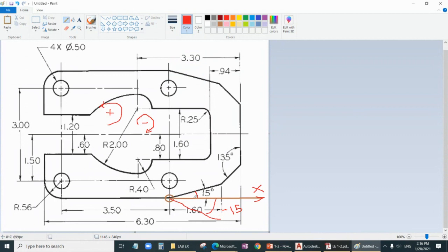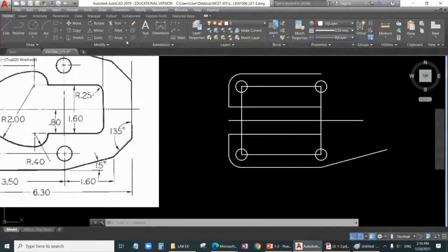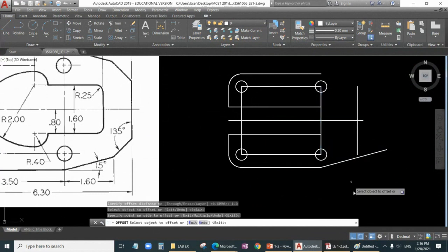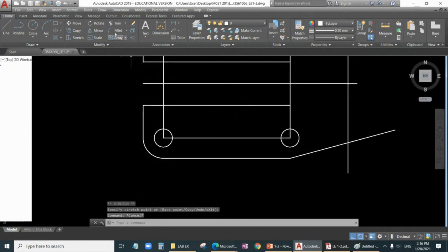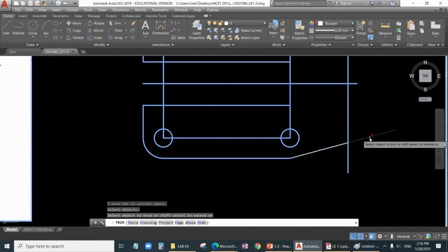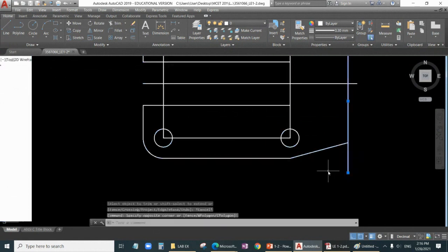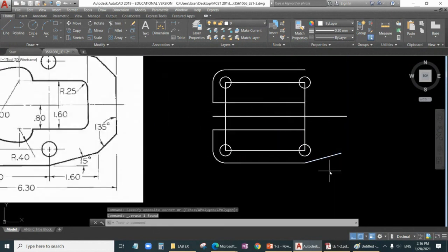Do we know the length? Horizontal 1.6. So this is a triangle. This is something different, so I took an extra length. I take it 3. Now we can go and see. We need 1.6 only, so 1.6 from this line. It should be here, so I will pull it down a little bit. We need only up to here, so I will trim it. Trim all. Enter, enter. I can trim that line here. Finish. I can delete this line. No need, this was just a construction line.